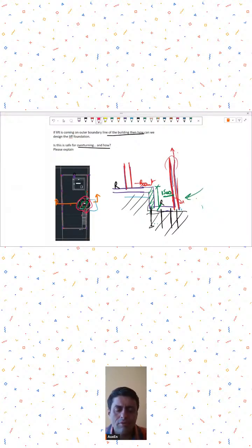Otherwise, around the lift generally you will not see a lot of issues. And the other way, of course, can be to thicken the raft for better load distribution. Generally around the lift, it's not loaded very heavily, though these columns might be, but otherwise it's not very heavily loaded. So it won't be much of an issue. If it is, then you can come up with these solutions.